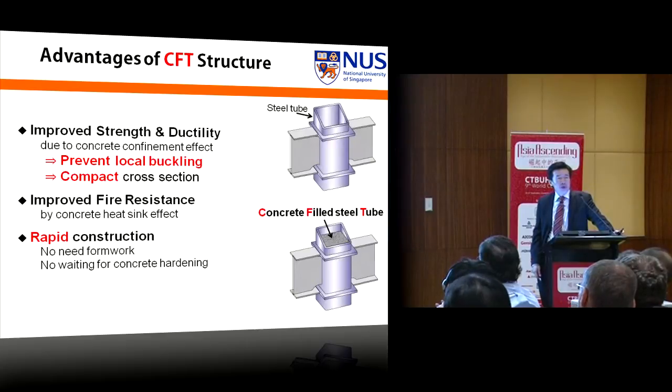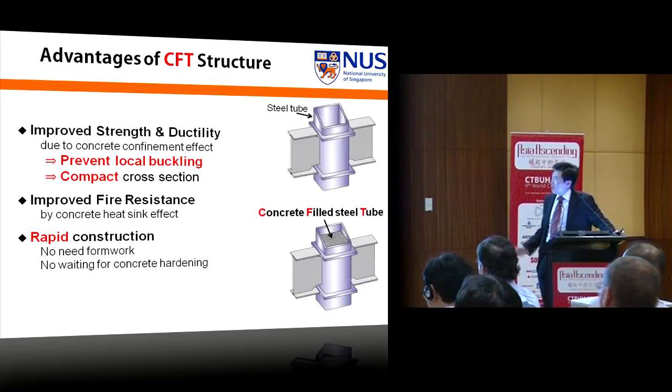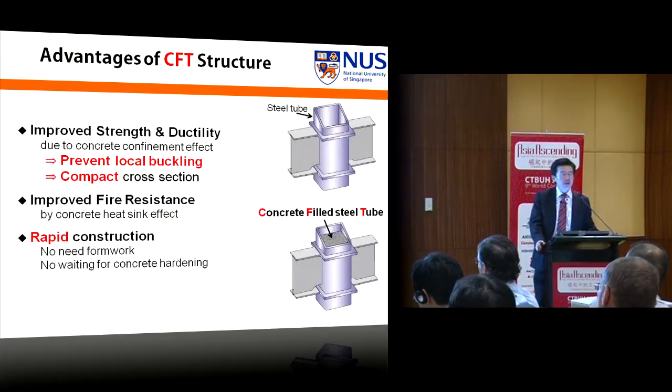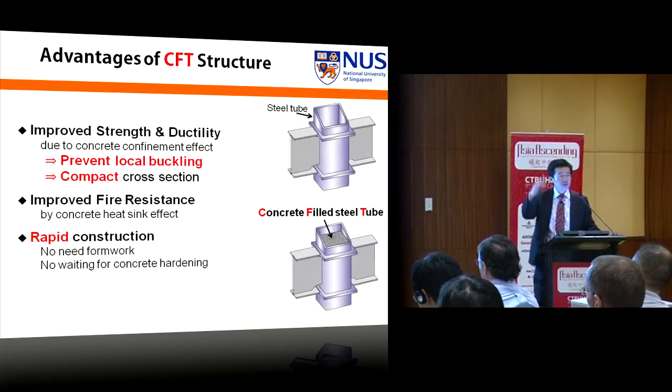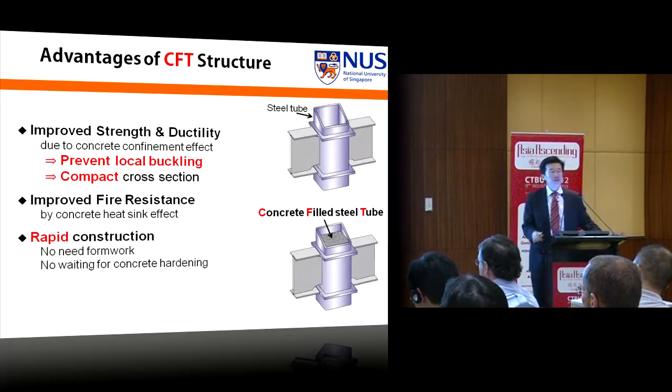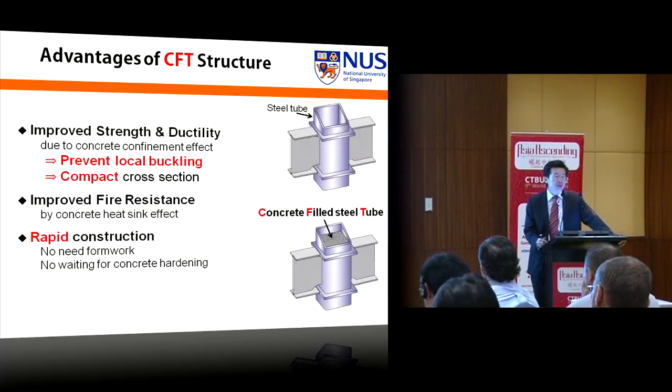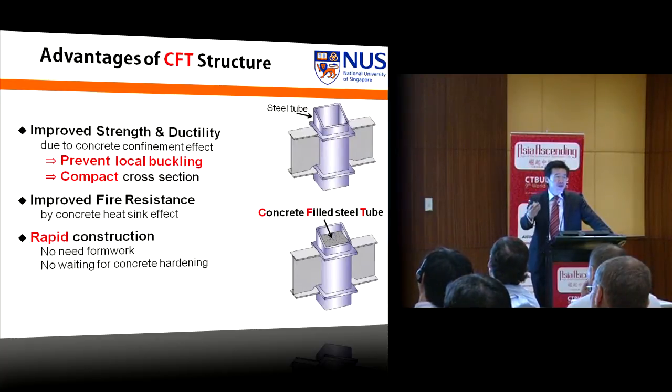to use a steel tube to provide confinement to the concrete. Now, this is called composite construction, steel-concrete composites. The advantage of doing that, compared to the normal reinforced concrete design, is that the steel contribution ratio has been raised significantly. In a normal reinforced concrete design, you can only go up to 6% reinforcement in terms of the volume content. But in steel-concrete composite, there's no limit to it. You can raise it beyond 20% up to 90%, according to the Eurocode guidance.